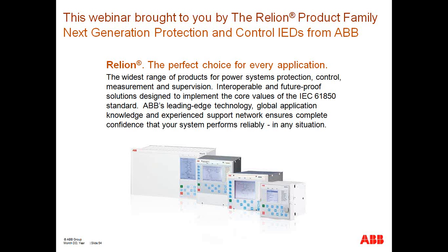Another question that I have here: does it mean the traditional RTU devices will lose their market with IEC 61850 applications? I think that, depending on the best practices of the particular customer and user, there's been a migration from RTU panels, from that initial architecture, to utilizing the data that's available within the relays to report it back to the SCADA or the control center. So there's definitely been a loss of market from that particular perspective. Now, 61850, I don't really think adds more to that loss.